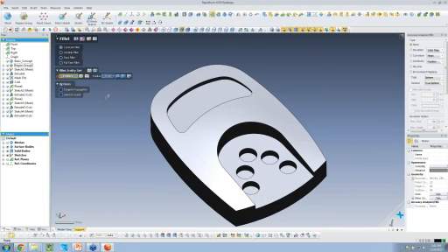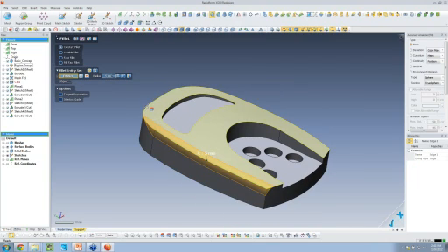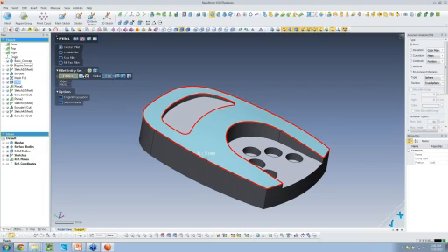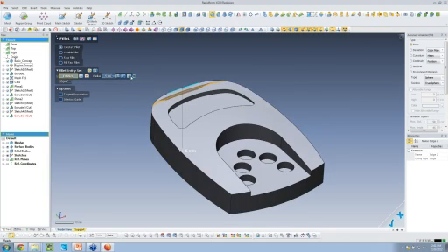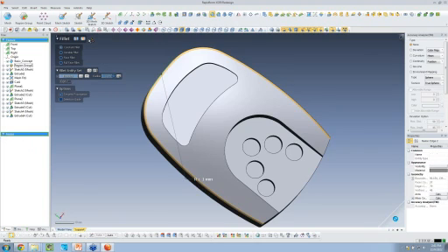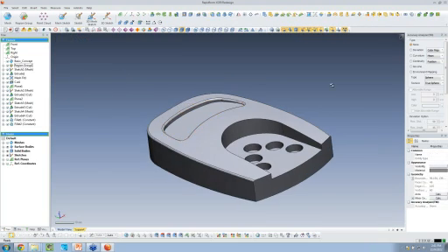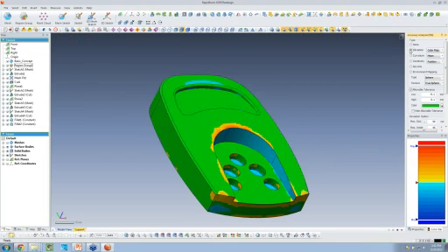So the last thing I need to do is I'm just going to add a couple of real quick fillets on here. And if I look at this fillet, you can see that 5 millimeters just didn't quite work. Let's back up. So 5 millimeters is a little bit too aggressive. Let's use this little toolbar here and say, let's estimate radius for mesh. 1.206. Let's round this up to 1. And let's select tangent propagation. It's going to go all the way around this part. And you can see that, real quickly, we can add our fillets across the part. And of course, I'm going to go to my deviation plot and look at this a little bit further.